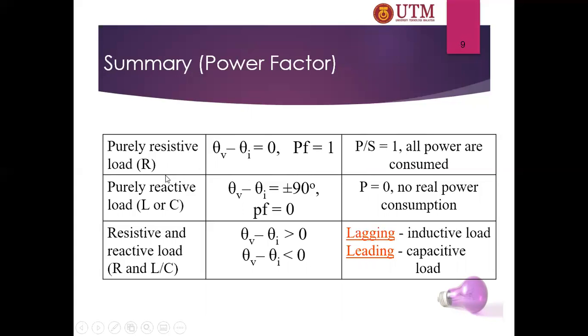Okay, and if your circuit is purely reactive, meaning either L or C, for example if your circuit is purely L, then theta v minus theta i will be positive 90 degrees, so the power factor will become 0 because cos 90 degrees is 0.